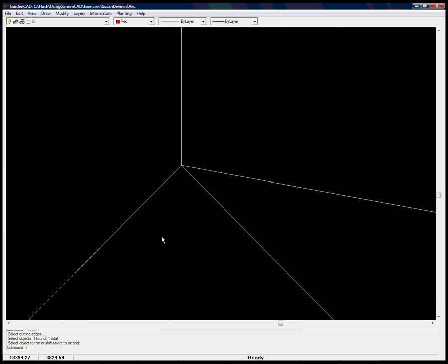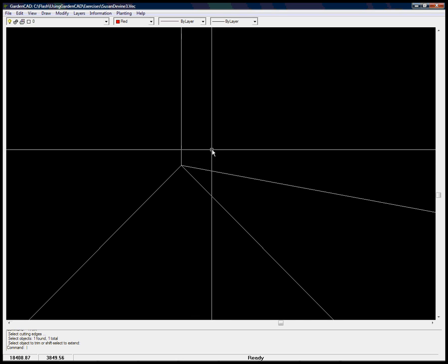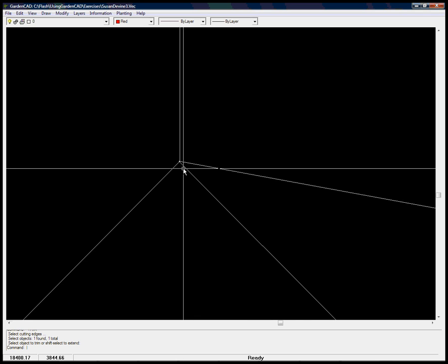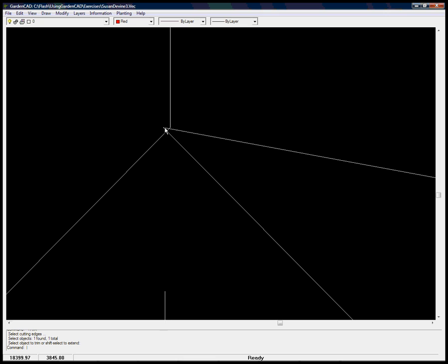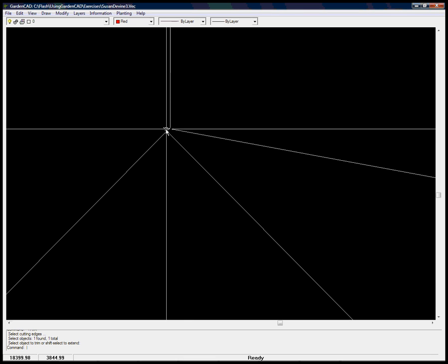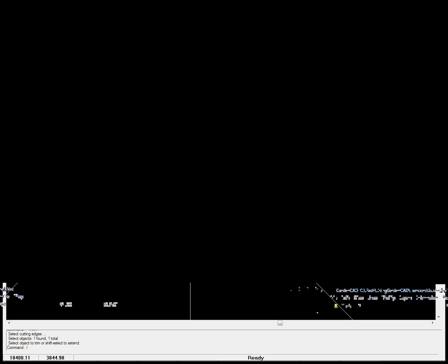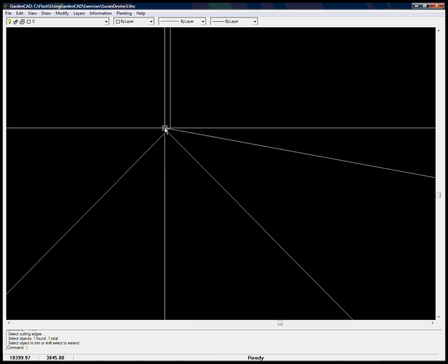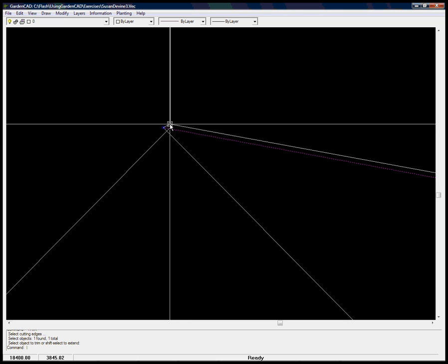We can also zoom in here. Now, as our piece of flat galvanized tubing that's going to support the wires runs across and attaches to the brickwork in the house, you can see I've got a slight error in here. You can fix that, and they clearly don't come to the same point. That would have happened because one of the entity snaps was turned on.